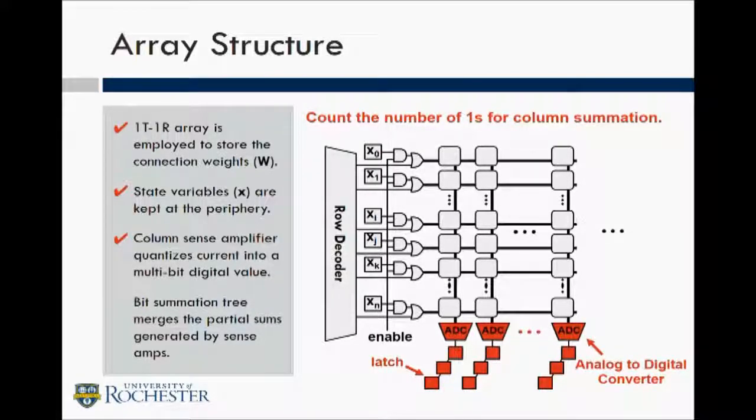We have a need to keep these A to D converters simple. Pretty much everybody who has since then tried to apply analog computing to these kinds of, or at least this array-based computing to matrix vector multiplication, has found that the technology is great, RRAM is dense, or some people use other technologies, and you end up with a tiny array and an enormous A to D converter that swamps all the area benefits that you came up with, unless you're very careful in imposing requirements on that ADC.